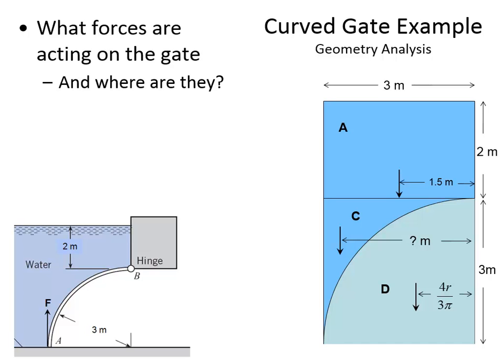So we had that the Y bar is 3.5 meters plus the area moment of inertia, 9 meters to the 4th, divided by 3.5 meters times the area of 12 square meters. Okay, that works out to 3.7143 meters.